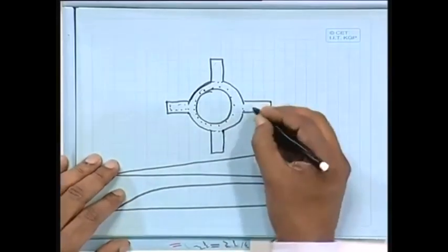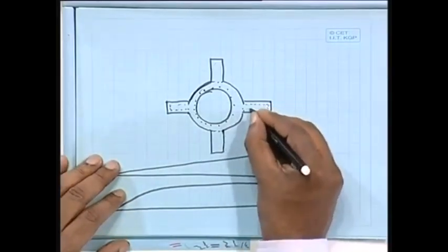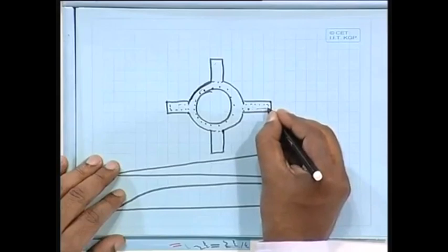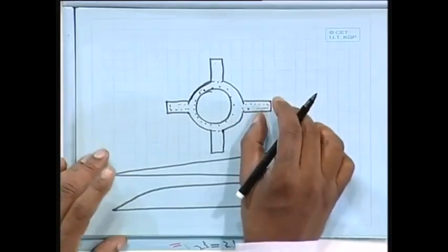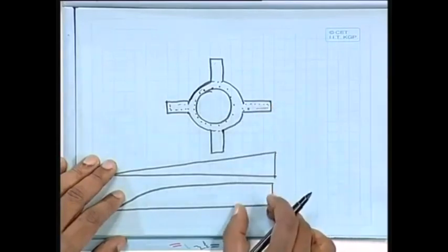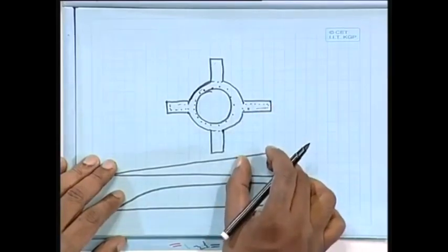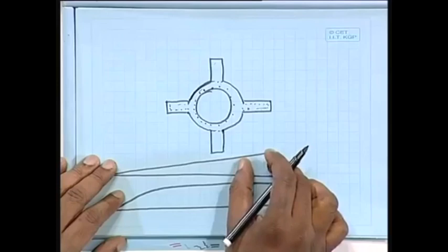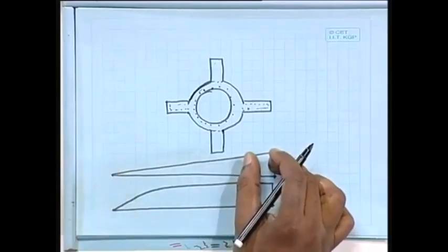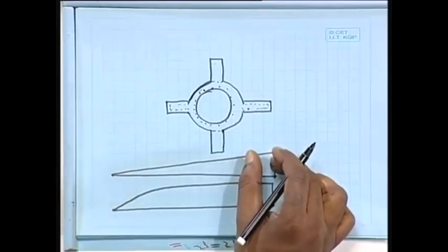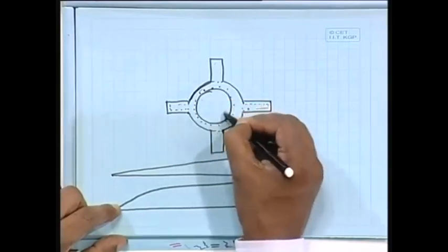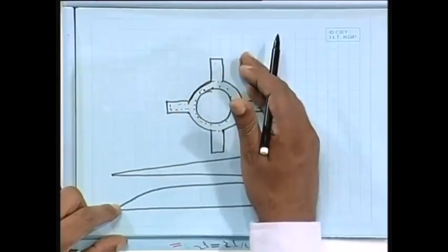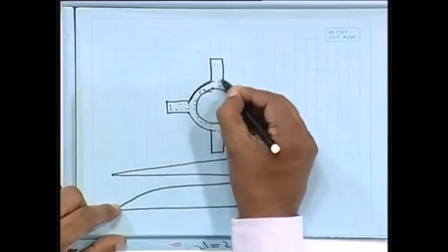and reinforcement along this. So many reinforcements you are providing. For each and every component you have to make it, but that itself you can do using only rectangular and circular. A rectangle that is placed here, what is the strain diagram, what is the stress diagram, you find out that portion, you individually compute what is the moment capacity and what is the axial load capacity. For this section you find out, for this section you find out and remove it, subtract it. Similarly for this one also.